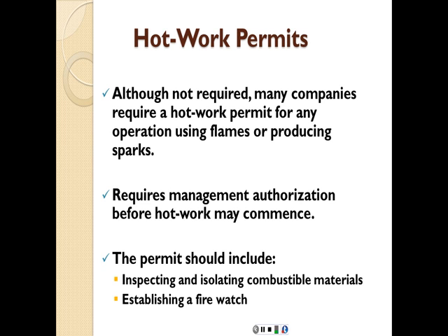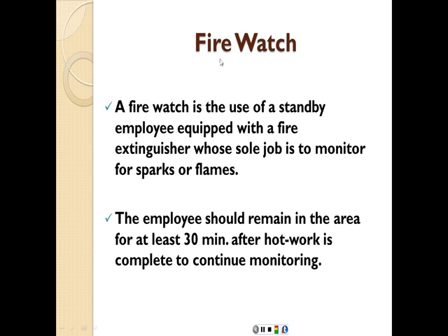And here we're going to talk about a hot work permit, which is a permit that's needed for certain kinds of work. Although not required, many companies require a hot work permit for any operation using flames or producing sparks. It requires management authorization before hot work may commence, and the permit should include inspecting and isolating combustible materials and establishing a fire watch. We're going to talk about the fire watch on the next slide.